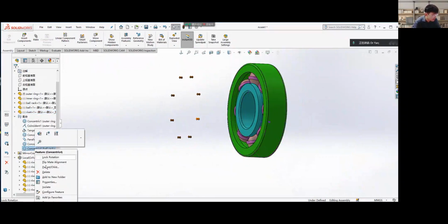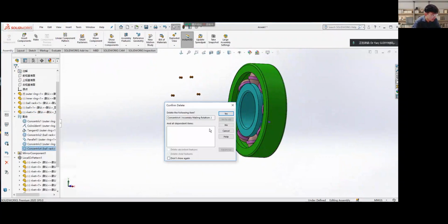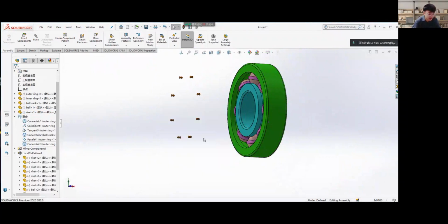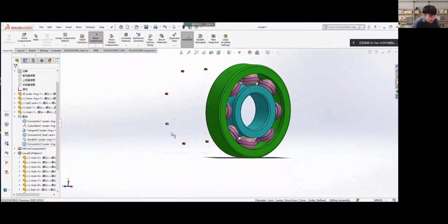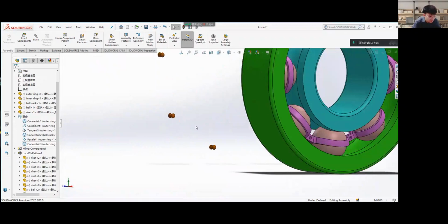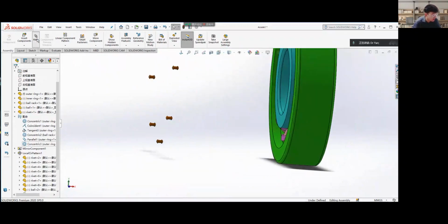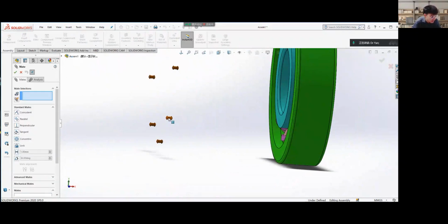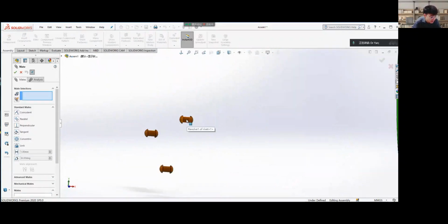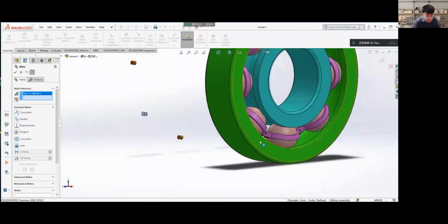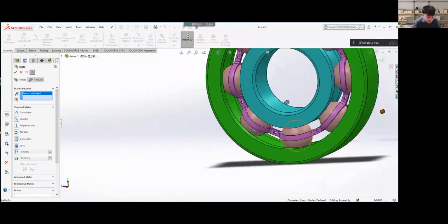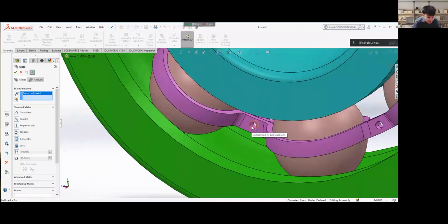And this one here is another mate I made on the rivet. Okay, I just did it. So now you can change the rivet. And now, first I just want to get it mated right here, okay? And select this cylinder surface right here, and into the hole right here, and just choose this surface.